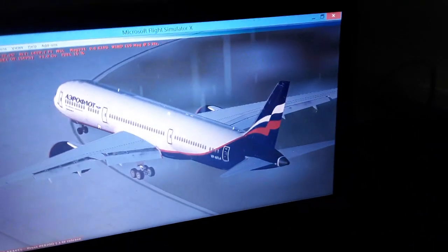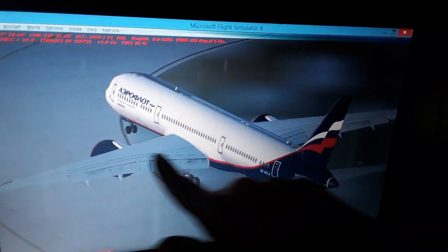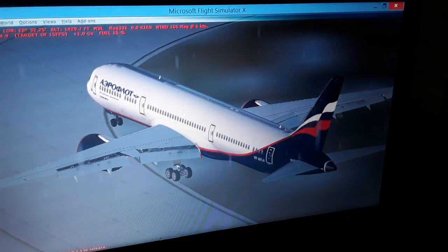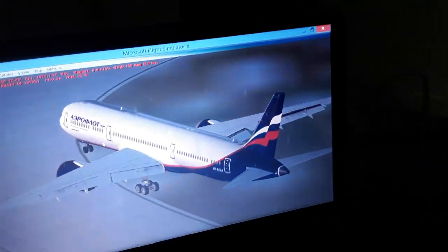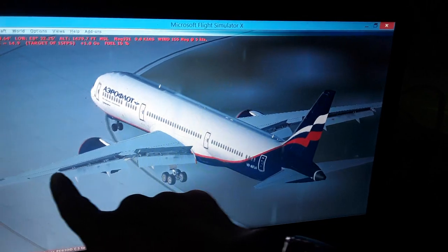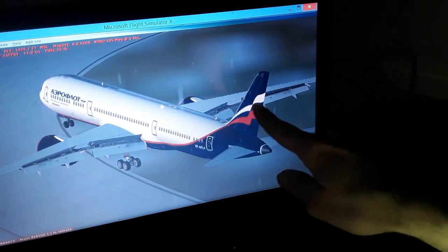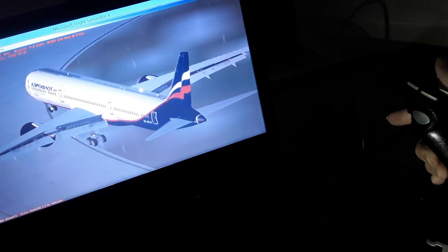So in the Boeing also we have ailerons and spoilers. You can see ailerons and spoilers when we deflect over here, and also we have the flaperon in the Boeing aircraft, one more surface. So you can see the spoilers now extended, also the aileron here and here. So we have the flaps also over here, down here, extended. So this is the control axis of the aircraft.